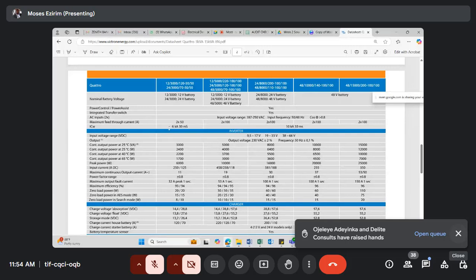Let me give you an example now. Let me assume the client's average load, all right, that's the energy. Remember, we are talking about energy in this case, not power. The energy is 10, you understand? You notice that the daytime energy for the client is 10 kilowatt hours. And the battery, of course, you've checked your battery charging capacity, and the energy that will be required is, let's say, 20 kilowatt hours.